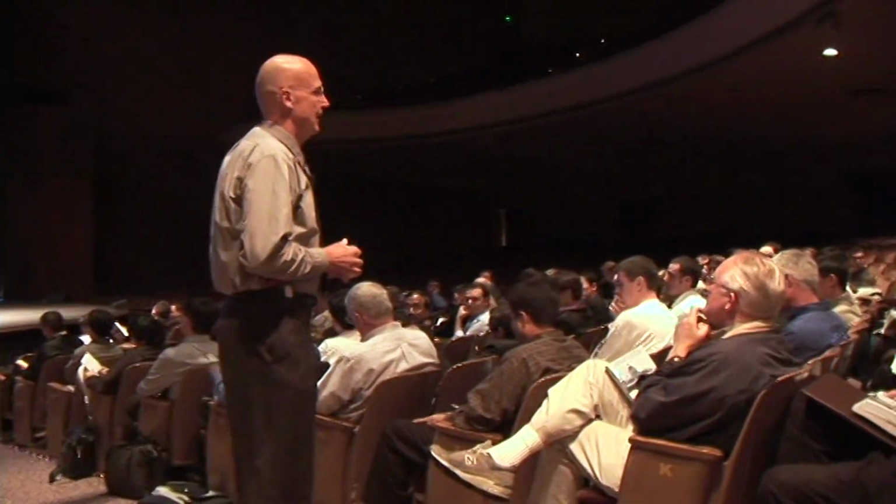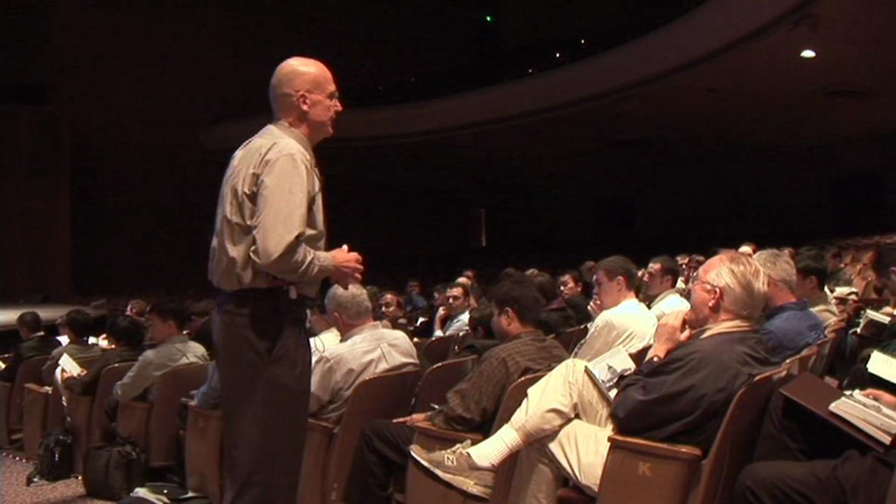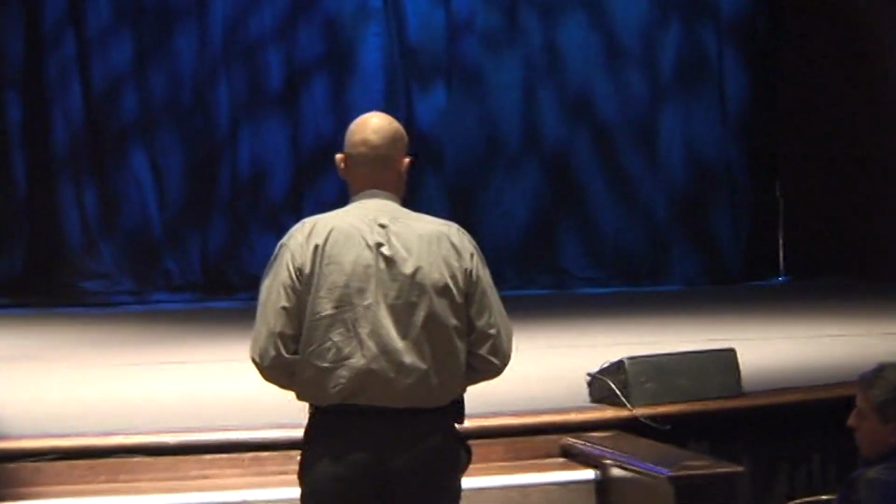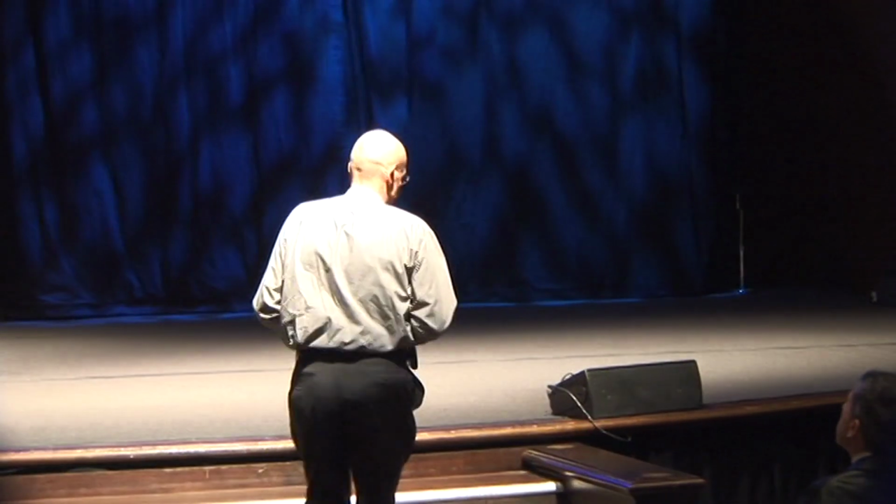Question. Okay. Now, I realize for the FEMA beam, you use the ASCE 41 parameters for the moment-rotation relationship. Can you not use that relationship for the plastic hinge as well? Yeah, the FEMA ASCE 41 gives you capacities for the chord rotation model.